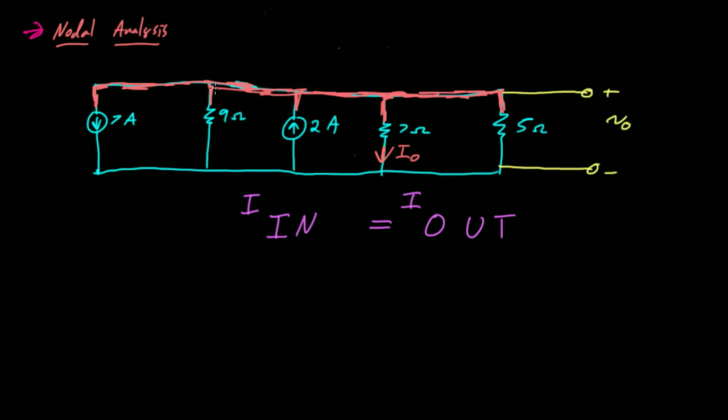And it is going to be at some voltage. Let's just go ahead and call that V0, right? Because if I say I'm going to ground this end of the circuit, that means that I've got another node here. Let me color in this whole node. So I've got another node that is everywhere on the bottom, and that I0 arrow is part of the node. So I've got this entire node on the bottom. And if I ground that side of the node, then this entire node is going to be at 0 volts.